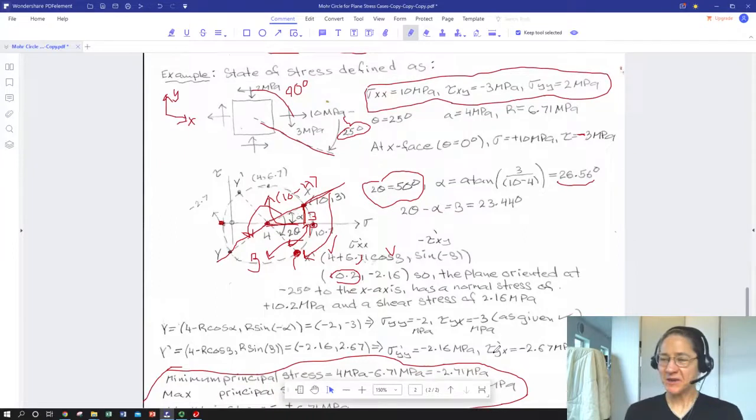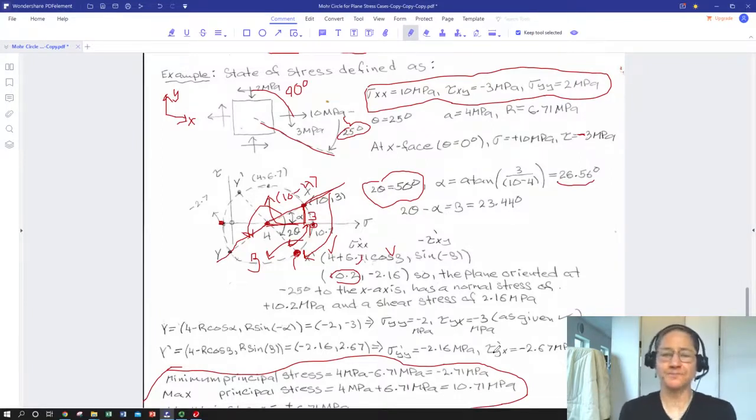So I am going to quit for this lecture here. This is kind of long and tongue-tied, but I'll just go over again. The Mohr circle is the same as our stress transformations in that we don't introduce any new concepts. It's just a mathematical rearrangement of the stress transformation equations. We start, rearrange equations, get rid of thetas. Notice we have a circle. We've defined the circle, center, and radius in terms only of our applied stresses, which presumably we would know.